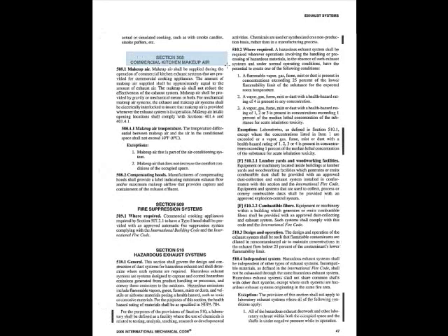Section 508 talks about makeup air. Again, an exhaust will pull a building into a negative pressure. So I have to have makeup air that will raise the pressure of that area by bringing in outside air to make up what I'm leaving. Section 509 talks about fire suppression systems, when it's required, where it's required, and it does refer to International Building Code and International Fire Code for more information on this. Now, what International Mechanical Code is saying, you have to go there to get the information. It's not part of the Mechanical Code. Do you still have to do it?